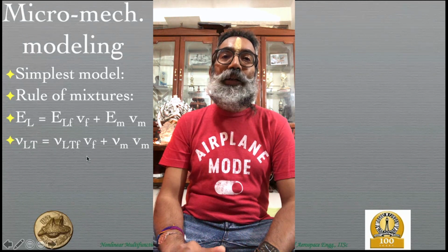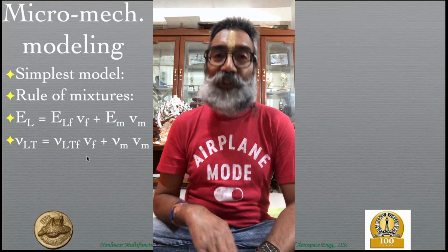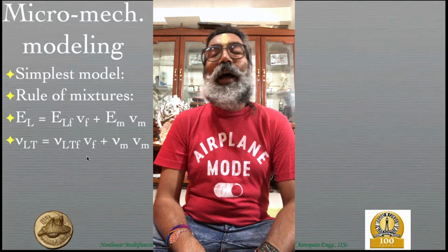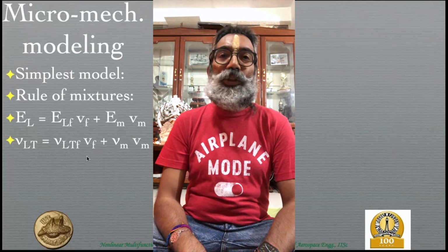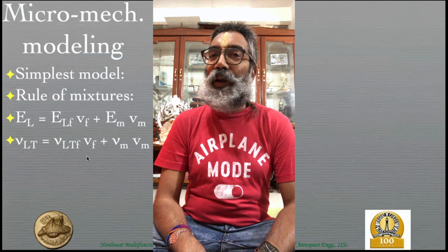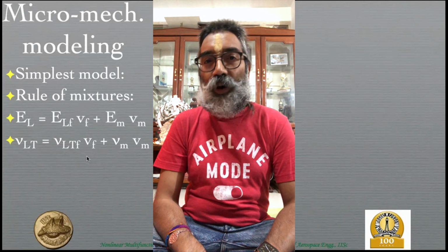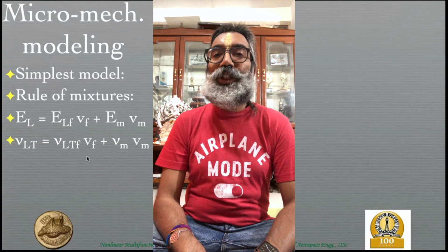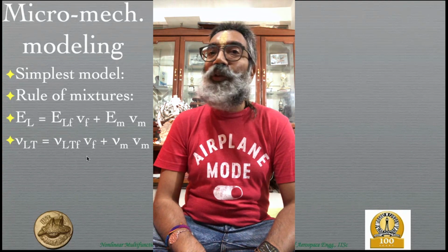Okay, so that is something that you should not be surprised by, because the derivation for the bulk modulus and the shear modulus will be different. So those expressions that you have for the bulk modulus and the shear modulus of an isotropic material are no longer valid for an anisotropic material like a composite, and therefore the limits would be a little more complicated.